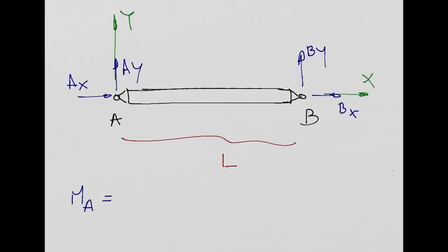Component in Y and X direction are going to be 0. So this moment I'm going to calculate now is the Z component of the moment vector. And if I start with point A, these two reactions at point A don't produce any moment about point A. You agree with me? Yeah. So I don't need to calculate the moment produced by these two.